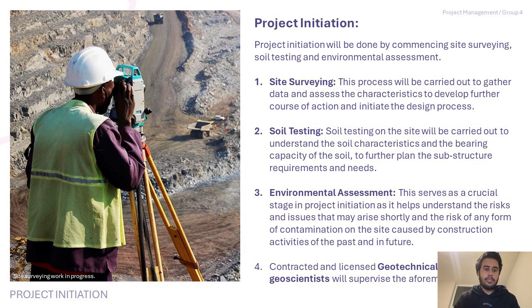So the site surveying process will include calculation of the grades, the existing grade on the site, and the elevations to understand the layout better, to understand the topography and the existing contours on the site. Then the soil testing is also an important part, wherein the consultants and the geotechnical engineers will get to know about the bearing capacity of the soil and all of those things. Accordingly, a structural design can be done.